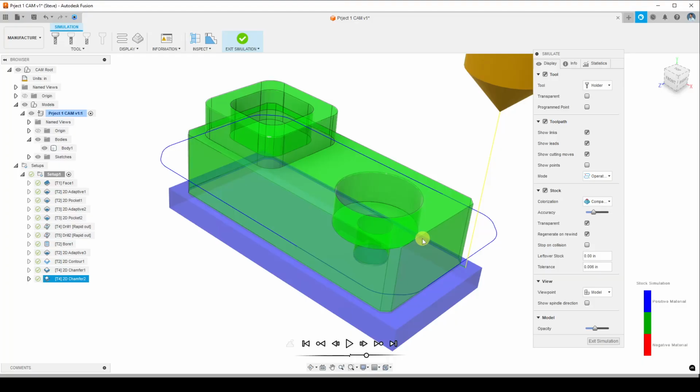The next step is, how do you make these toolpaths into G-code for the machine to run? That's called post-processing. In the next video, we're going to post-process these toolpaths, and we are also going to create setup sheets. That's for the machinist. It's going to have all the details on this program, things that the machinist needs to know when they're at the machine. So we're not quite done yet, but we are getting close.